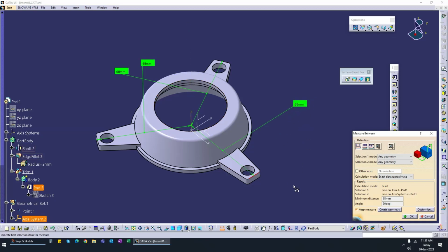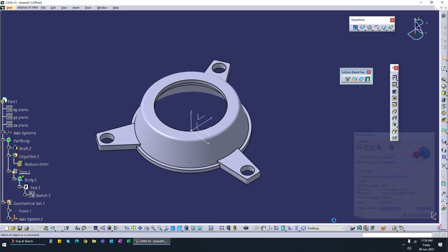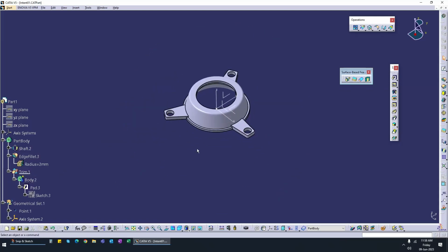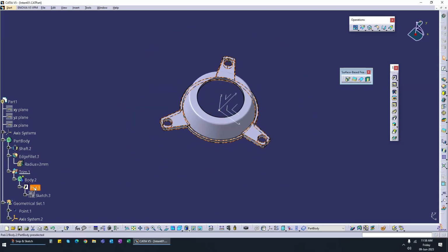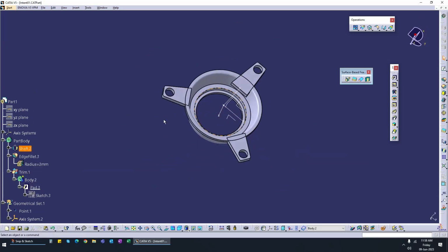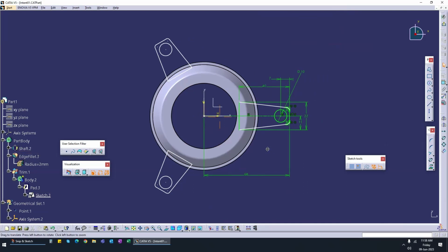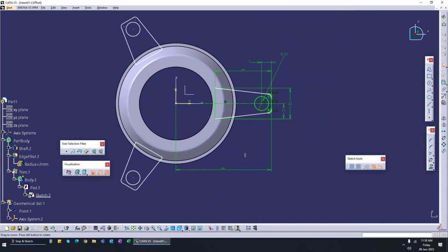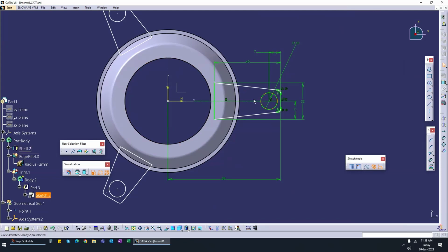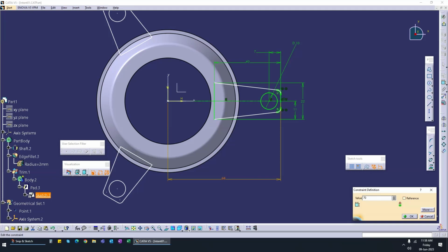it is 68 millimeters. What if we want to increase this length from 68 to 70, or we want to decrease it from 68 to 65? Let's try doing it. So we go to the pad feature, we define it, where we generated these three pads. We go to the sketch for the pads, and here we will try to increase the length of this tab by 2 millimeters. Say from 68 we want to change it to 70, and we press enter.